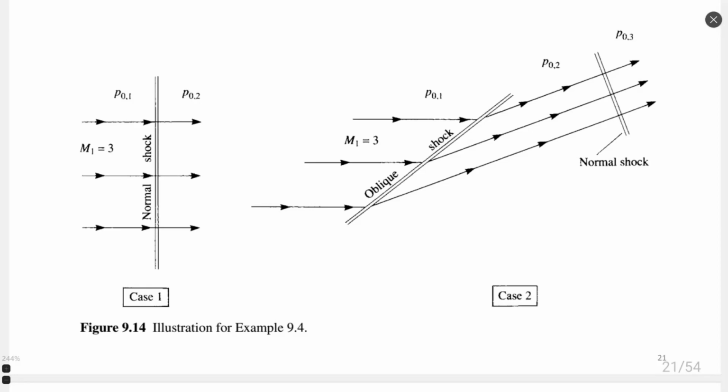this. What is the importance of Mach angle? We will see it. Still in this chapter, it's used widely in expansion waves, because expansion waves are related to propagation of disturbances, and Mach angle purely gives the direction of the angle of disturbance propagation.